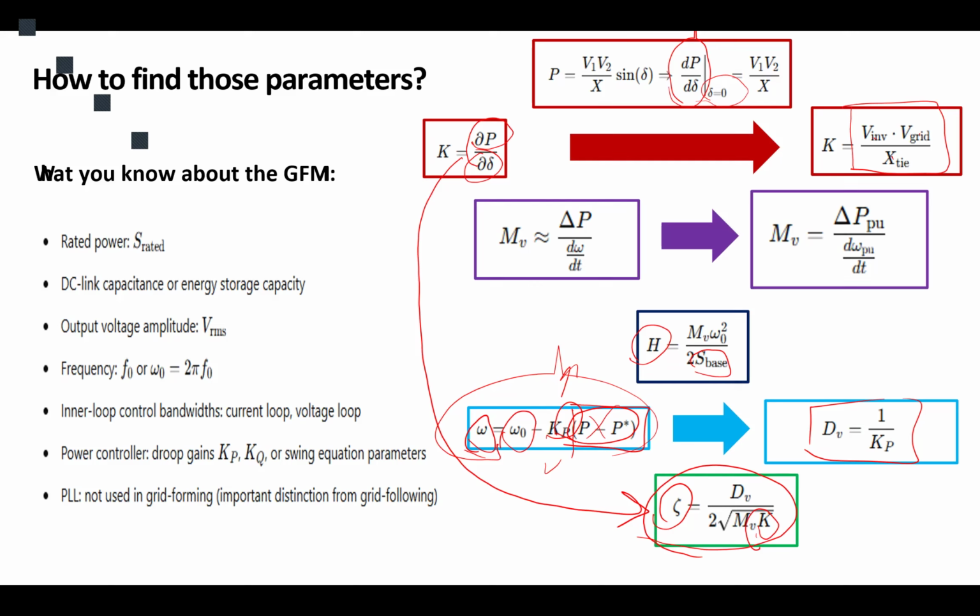Okay, this damping factor defines the fast transient of your phase angle. You create a fluctuation in your system. That fluctuation would create a very fast change in your frequency or your phase angle. This damping factor is the ability of your control system to address that fluctuation. What a filter does is eliminate the high frequency variations, so we don't consider that.